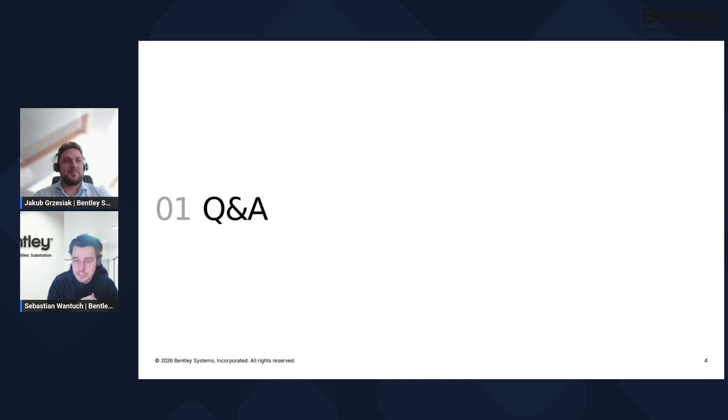Yeah, first of all is the better visibility of the whole substation model. As you know, there can be thousands of different clamps, cables, and so on. In 2D, it's a lot tougher to see any changes or any clashes than in 3D. Another thing, especially if we are talking about a GIS substation, when you have the gas insulated substation inside some kind of building, is that you need to coordinate between the different design departments.